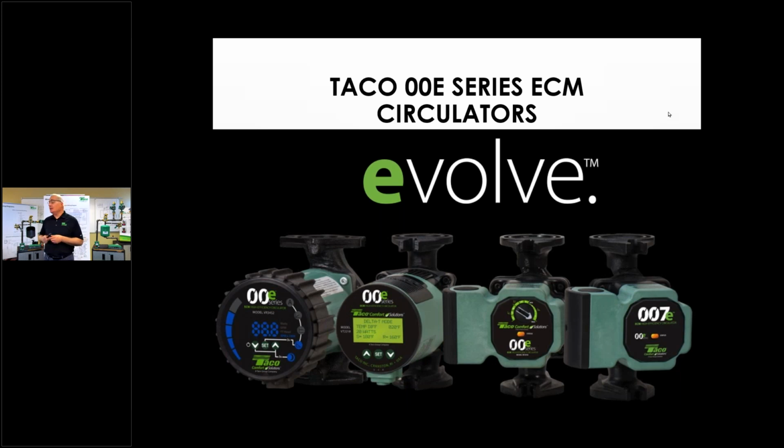Why not have the circulator, which is the heartbeat of the system, be able to adjust its speed based on zones opening and closing, either by a pressure differential, or if you really want to nail it, by a temperature differential, a delta T. Especially if my boiler is going to be modulating based on outdoor temperature and demand, if my circulator can maintain a specific delta T, it makes for a much more efficient and comfortable system, okay? Take advantage of these as you can.